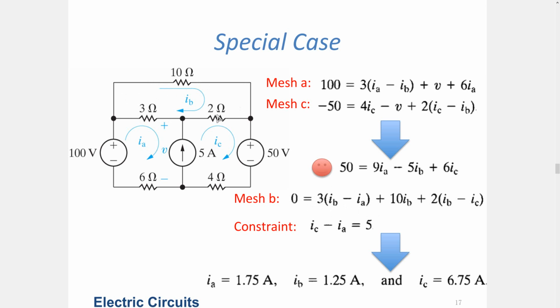And here, again, in the 2 ohms case, I assumed that the current flow is from left to right, so I'm opposing that. Because of that, I should write down minus 2 ohms times IC minus IB, which can be converted into 2 times IB minus IC. I'm just rearranging the terms, distributing the minus 1 into the parentheses, should be equal to 0. Okay, I end up with this equation.